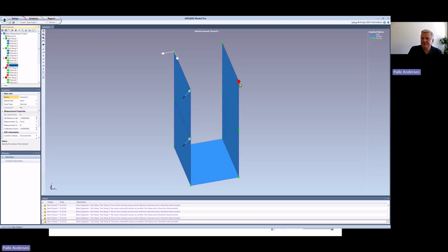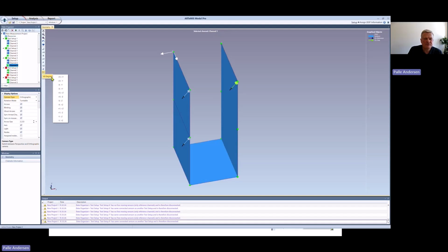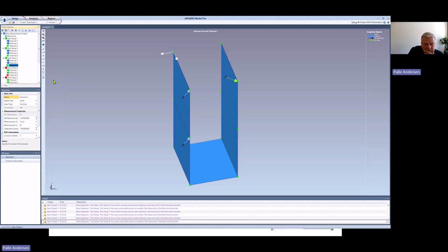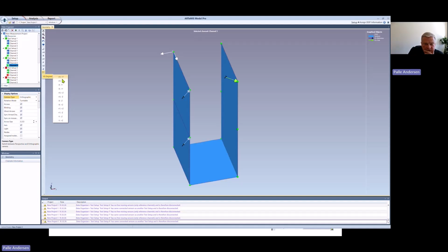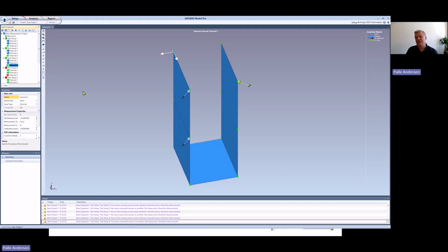And then the next one I can drag over here, and now it has this direction, but maybe it will be easier if I go this way. So if I go to 45 degrees again, and then I use, is it minus X then? Let's see. No, not that one. So we try again. We have minus X, and then we have plus Y. Yes, this one. Now it's in the correct direction, and we can repeat it one more time. It remembers the last direction when next time you drag one of these out.